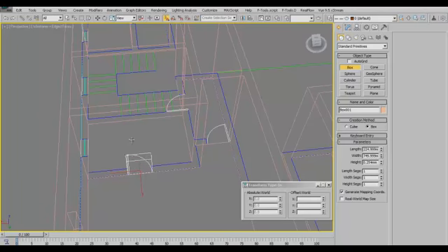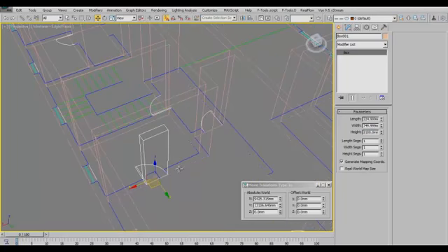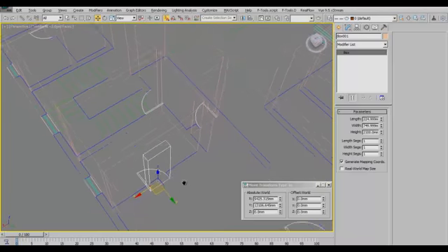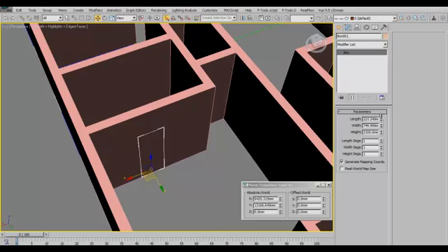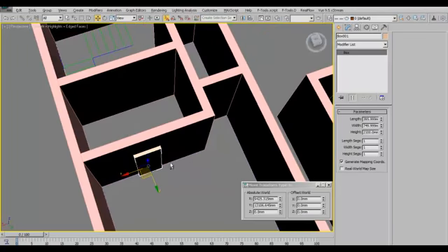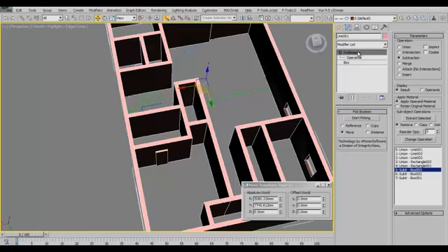Of course, because the door is going to be 2001, you're going to have to make it 2.1 high, and just as said, make it more than the original thickness of the wall, so we can Boolean well out of it. Then you go back to your boolean, and you pick, and you make sure it subtracts, then you subtract that.